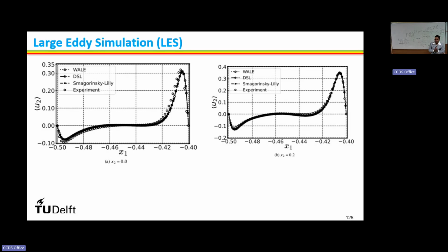So you need to minimize your grid error due to grid size, error due to your numerical discretization or numerical scheme, error due to any non-conformal interface. If you minimize all sorts of error, then your results will be as reliable as possible.